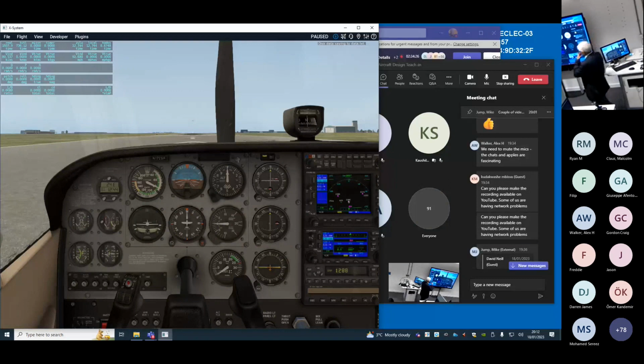I would really recommend you look at the control layout. Okay, so what you do, adjust any trim controls and advance the throttles and manage the rudder, keep the aircraft on the center line. We go back to that menu, wait for the speed to build up. So the speed is 55 knots. So that I think is about 55 knots.